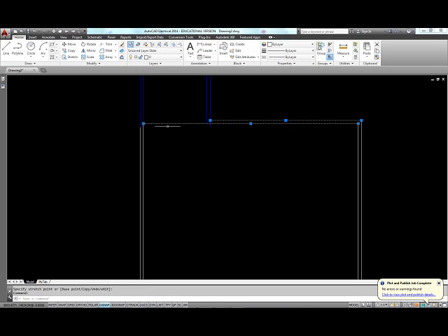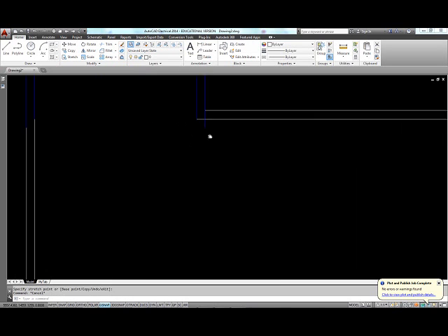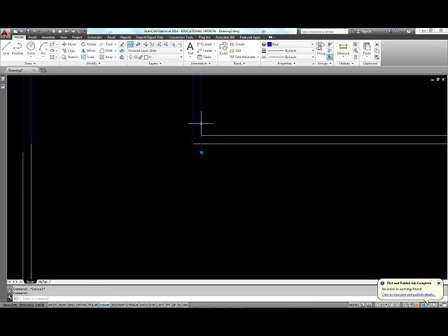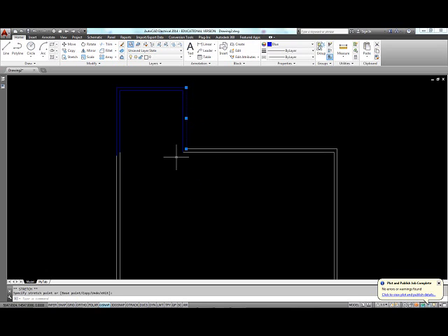I will choose the other line and then choose this handle back to this end. Can zoom in a little bit and pick up this blue line, take this handle and then click back. Now I have a clean corner here. I would like to avoid duplication of lines, so I want just one line each instead of 2 segments.